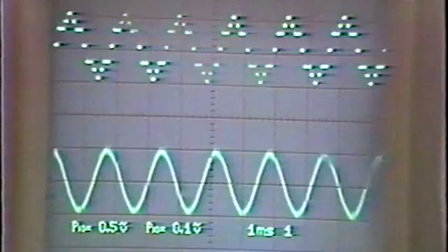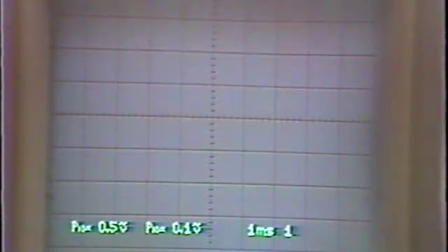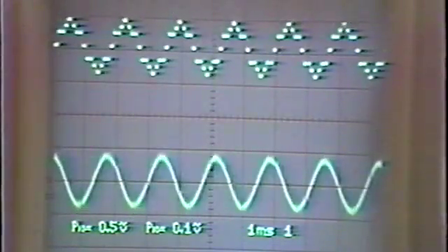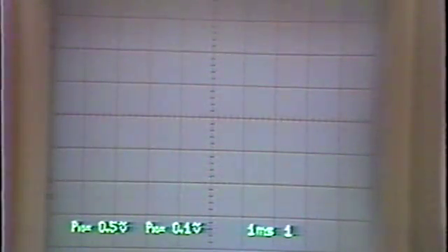The filter converts the stepped waveform to a smooth waveform. The waveform at the top is the filter input. At the bottom is the filter output. The filters also cut unnecessary frequencies according to selected tones. There are three different types of filters: a low-pass filter, a high-pass filter, and a band-pass filter, each passing a different frequency. The low-pass filter is mainly used with the Casio tone.